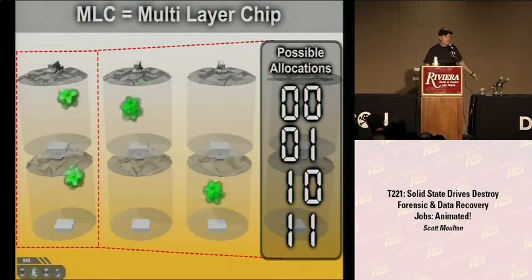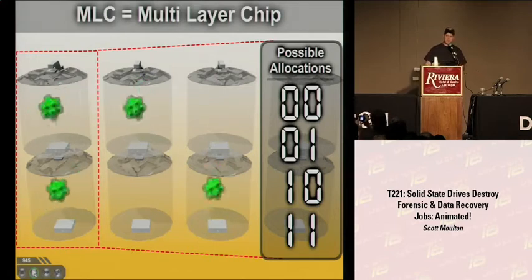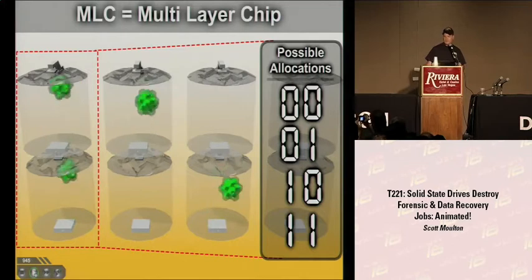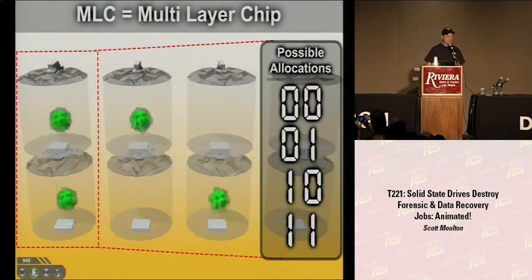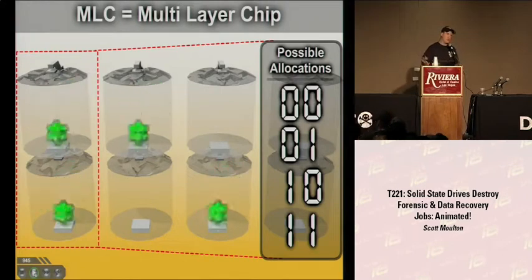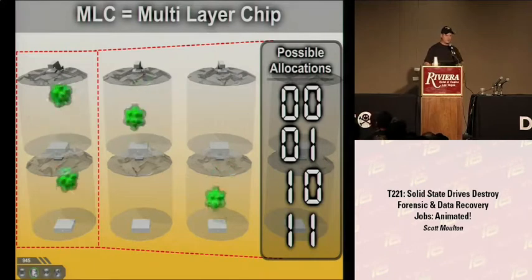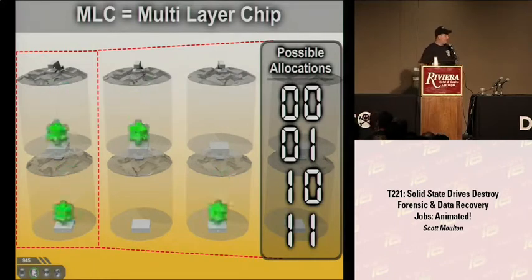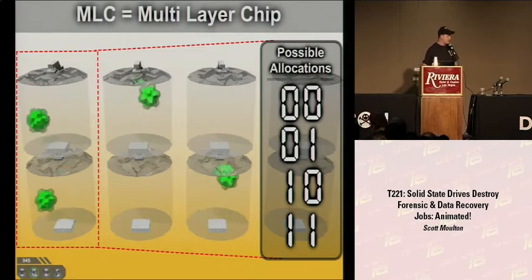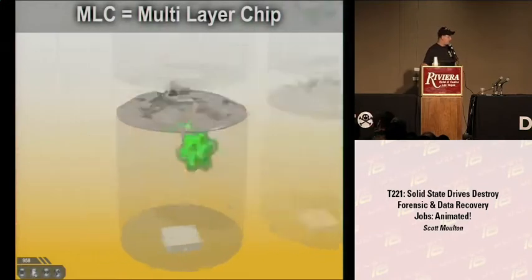What you have to understand about MLC versus SLC chips is that if it's SLC, it's faster. It's going to be somewhere in the neighborhood of maybe 30 to 40% faster than an MLC chip. So when you start seeing costs coming down and really big gigabytes of storage, just know that it's not going to be as fast as an SLC if you're looking for performance, unless they've made some modifications to improve speed. But you have plenty of combinations now of the way you can store data.